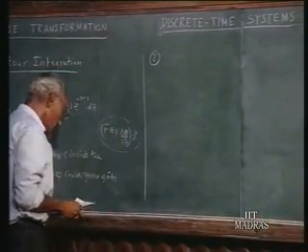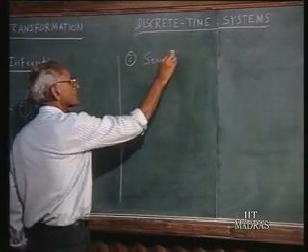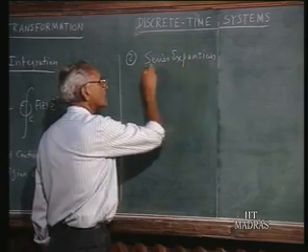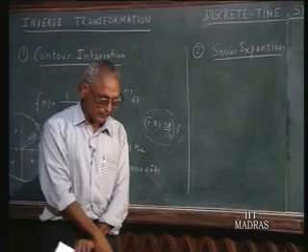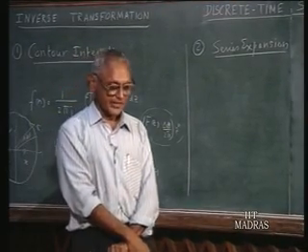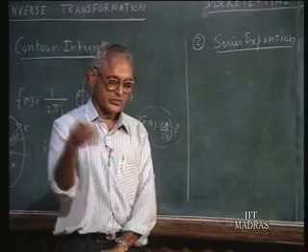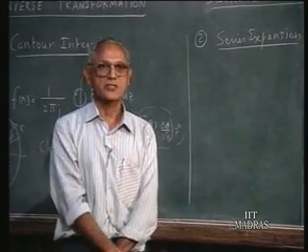A second and a very simplistic method is the series expansion. Suppose we are given F(z) and you expand this in ascending powers of z^-1. Then each coefficient of z^-1, z^-2, and so on defines the value of the sample at appropriate instants of time.